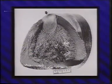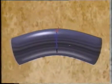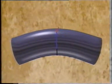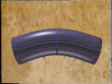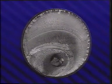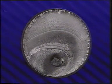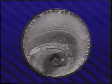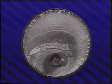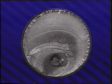in torsion. When a crack has grown to the size at which it significantly reduces the load-carrying capacity of the part, a change in the direction of crack growth usually follows. In many parts, the fracture may, in general, still appear flat, but if the level of operating stress is low, the surface appearance becomes rougher and more fibrous. This indicates the change from crack extension to the final fast fracture. Notice there are no beach marks in the fatigue area. This is because the cycling in the test was continuous.